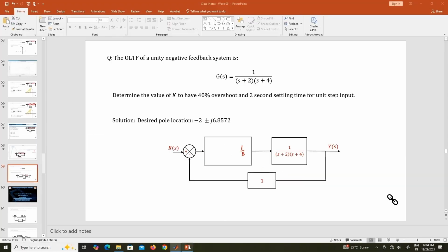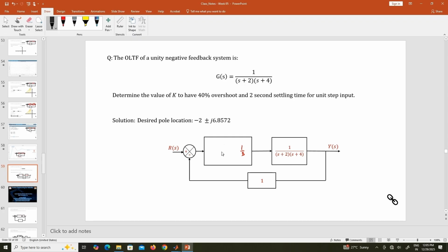The issue is that the 0 that you are introducing is very near to the open loop pole. Okay. So there is a chance of what is known as pole 0 cancellation. Think about it. If I go back to the diagram that we had, suppose you introduce a 0 at this position, K (s plus 2). Then we have gone for this type of a design, right? 2 or 2.04, something like that. So if I find out the open loop transfer function, these two will get cancelled out, right? This cancellation is an issue.